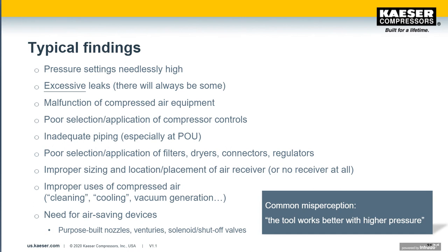There is water downstream, opening up some valves, bottoms, etc., drains. Then you need to talk about drains, dryers, and valves, for example, bypasses around dryers, which have not been closed. Multiple compressors in the system, maybe even spread around all around a building or various buildings with no common or master control.